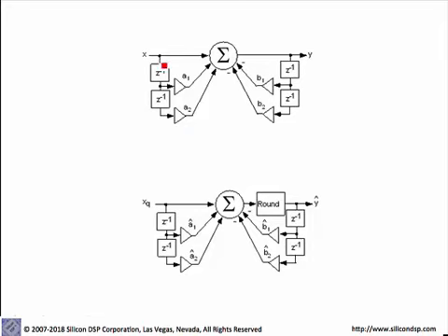Here we show the implementation of a Cascade section. We have the input basically delayed, going through a tap delay line. This is a biquad. So you have the weights for the input delayed, and you have the weights for the output, which are fed back and subtracted from the inputs in this accumulator here. So we are very interested in this architecture because we accumulate all the results of the multiplications so that we don't have any round off errors after each multiplication, but we actually accumulate them so there's no errors, and we're going to only have an error after rounding off of the accumulated results.